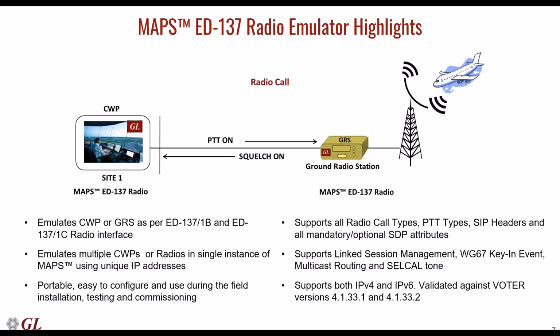We do support all the radio call types and the PTT types, and we can also modify all the SIP headers and the SDP attributes related to ED-137, which have been defined in the specifications. Apart from that, it also supports advanced features like link session management, multicast routing, or selective call tone transmissions.